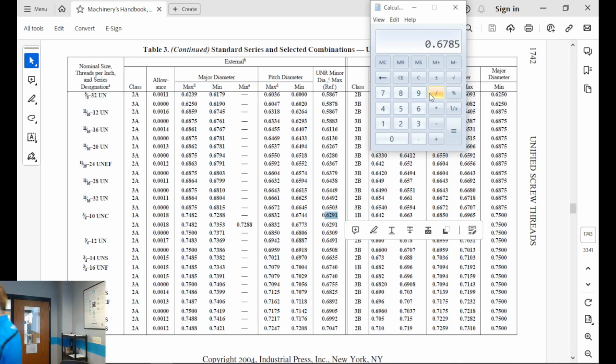I'll measure my thread pitch with my mic. If I'm at .680, that's a little close. If I'm at .688, I'll adjust that thread 5 thou, recut it, and measure it again. If I'm on track and it's cutting correctly, and I've got 5 thou more, then I'll go 2.5 thou. When I get within about 1 thou, that's when I start trying to fit my gauge on there. Has anybody ever used thread gauges before? Like go, no-go thread gauges?